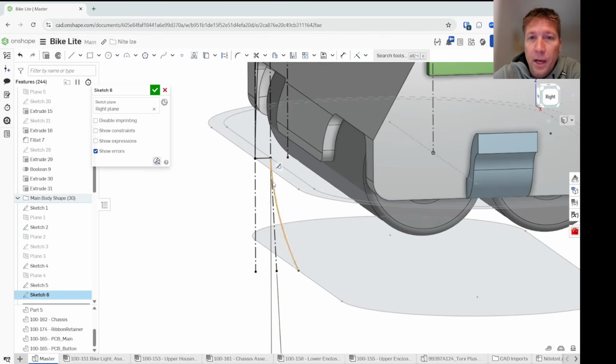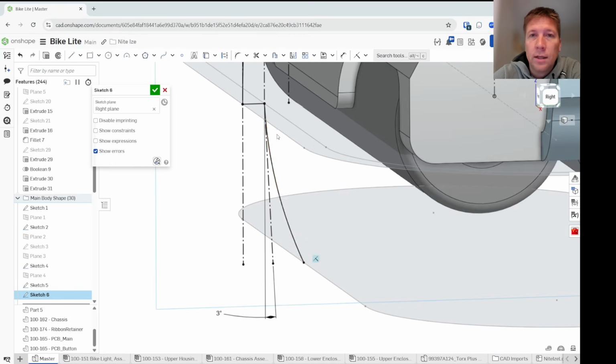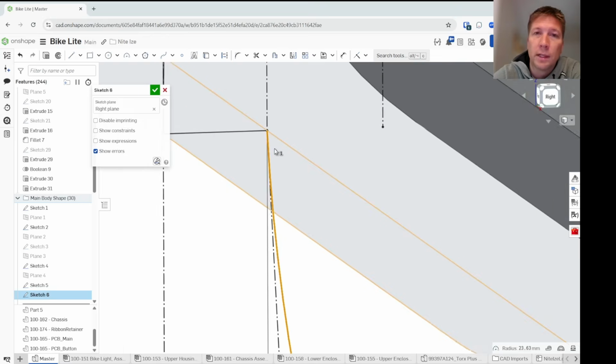This one, I'm putting a vertical line right here, and we're defining that draft angle as a minimum of 3 degrees. So this line comes into that line and becomes tangent. So this line guarantees that this line will never lose that 3 degrees of draft at the parting line, or at the bottom of that surface. If this ends up being at 0 or even above 0, we get scuffing, or we get parts that get retained in the mold and can't be removed.